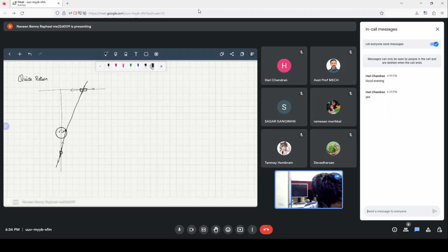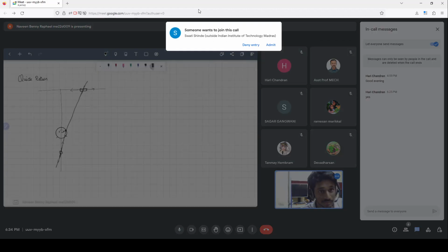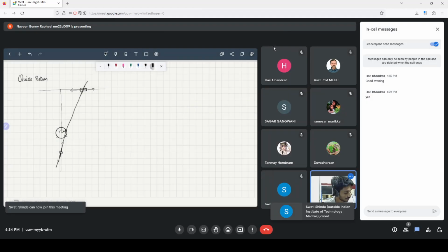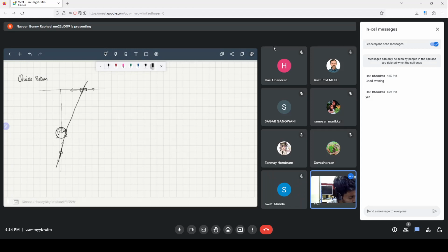When you're rotating on the further side of the circle, it will slowly go to the other side. From this angle to this angle, the crank will take so much time to rotate through this region, and in that time, this point, where the end effector is, will slowly move from here all the way back to here.